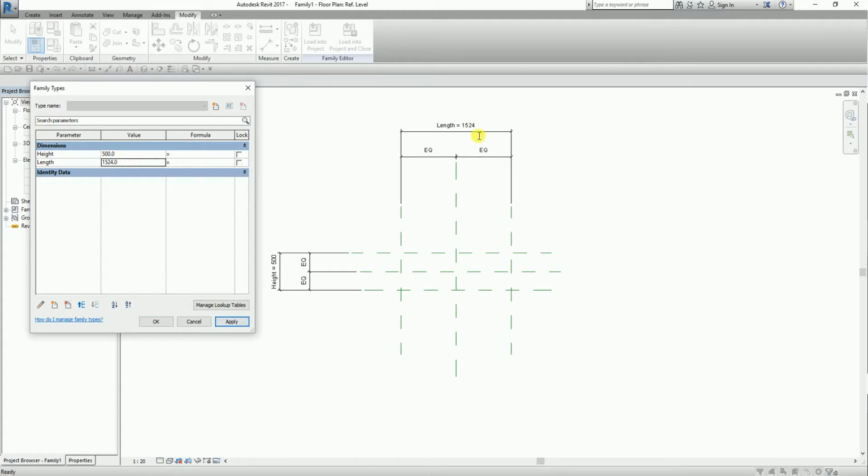So Revit will convert that for you. So let's say for the height, my given is 40 inches. Just type 40 and then include the inches symbol in case you are using a metric template. So you can still use your English dimension. Just include the unit symbol.